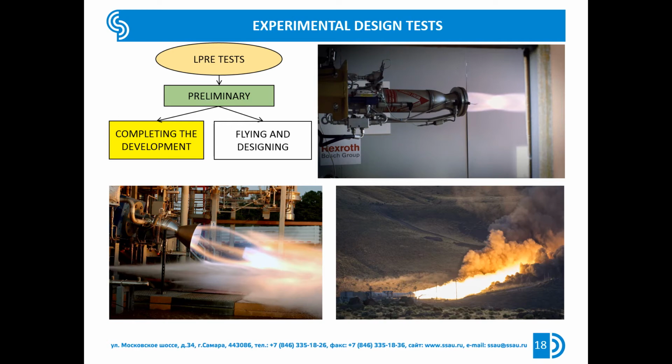Propulsion system tests are conducted mostly in terrestrial conditions. In some cases, where the propulsion system parameter level allows the use of high-altitude test benches, tests are conducted under simulated operating conditions. During bench tests of liquid propellant rocket engines in the propulsion unit, the launch and shutdown of the liquid propellant rocket engine under pressure failures and water hammer in the standard lines of fuel component supply are checked and, if necessary, finalized.